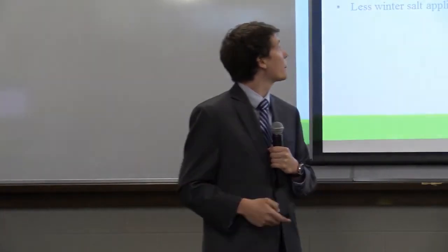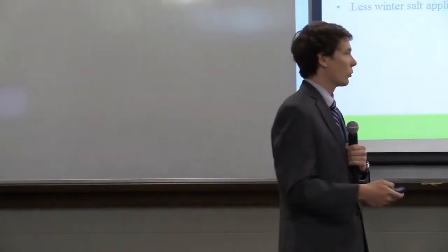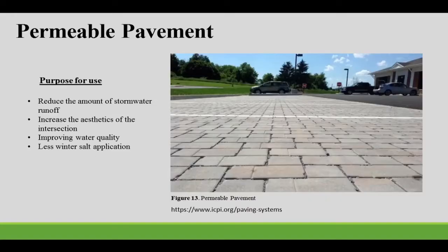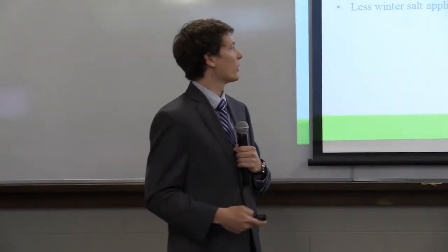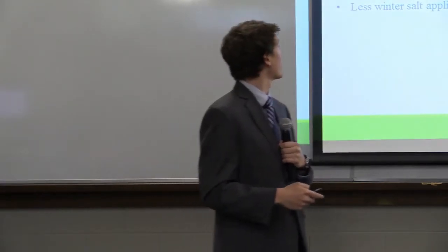It looks nice. Also, we're using a permeable pavement for some of the same reasons. We get that storage and that water quality benefit. And not only that, but they're better than normal concrete sidewalks because of the less salt application in the winter. Instead of with normal sidewalks, where water sits on top and freezes, with these, water is able to infiltrate into the cracks rather quickly, so it doesn't have a chance to freeze.